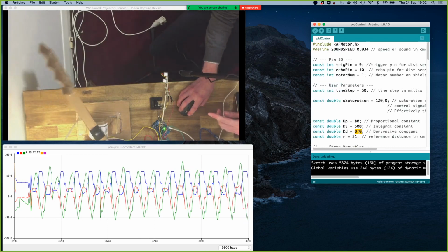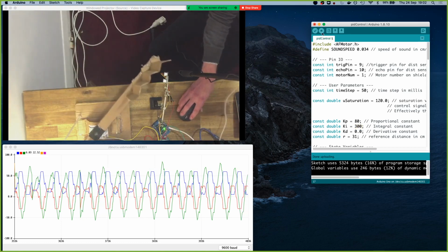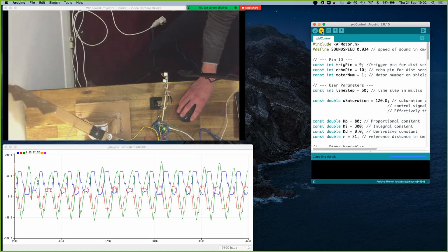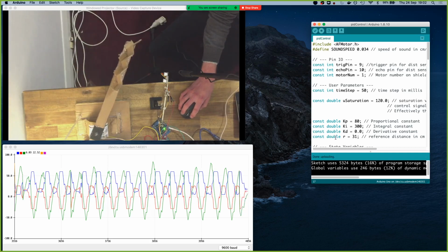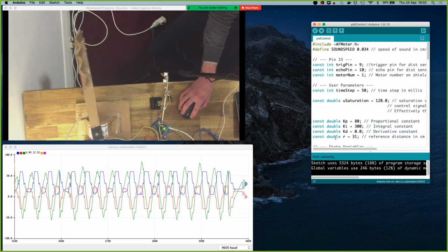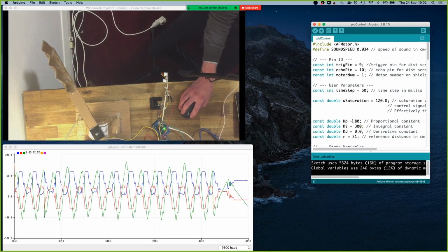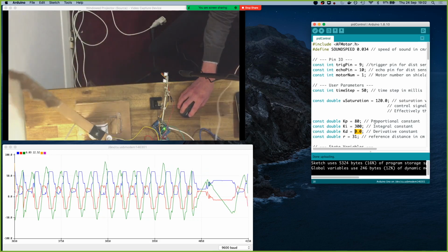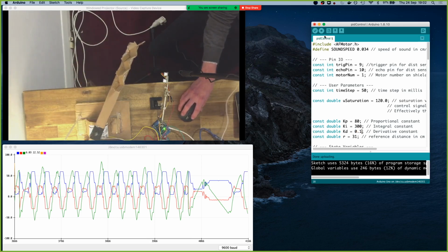Let's drop this down a little bit. Let's go maybe 300, and then we'll bring in some derivative term and see what happens. Come on, upload. Yeah, so that's doing something. So let's bring in some KD. Even just a little bit I think was okay, and we can start seeing what that does.